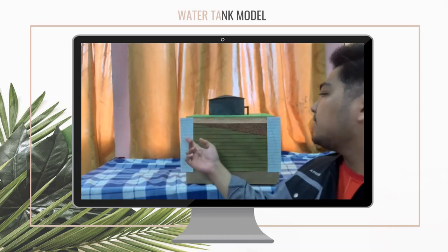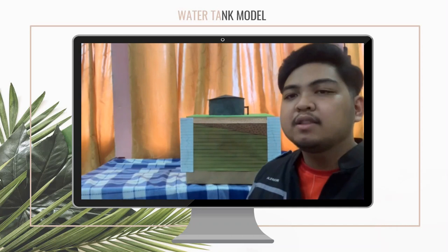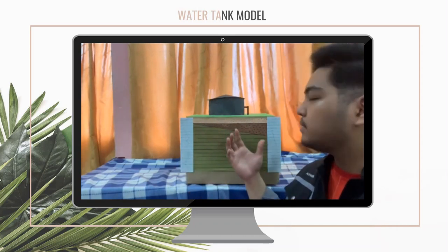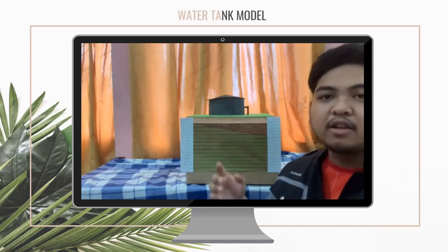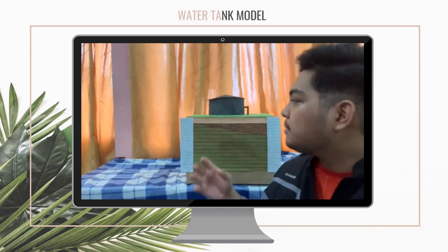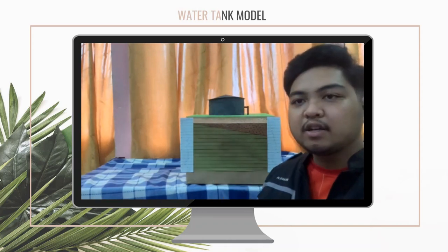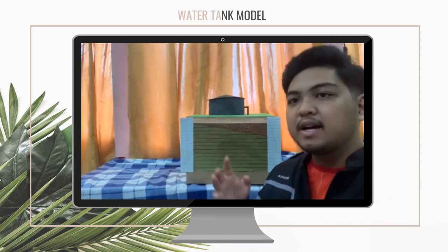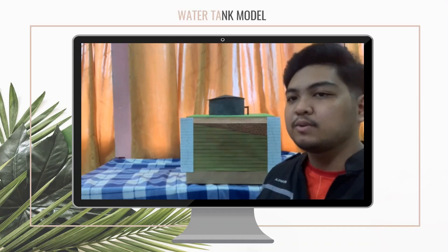Here you can see that there are two boreholes. According to the site investigation report, the soil in borehole 1 and borehole 2 were topped with 0.3 meter of topsoil. The topsoil here is sand. From 0.3 meter to 7.5 meters, the soil profile of borehole 1 is soft clay, with standard penetration test values ranging from 0 to 2.